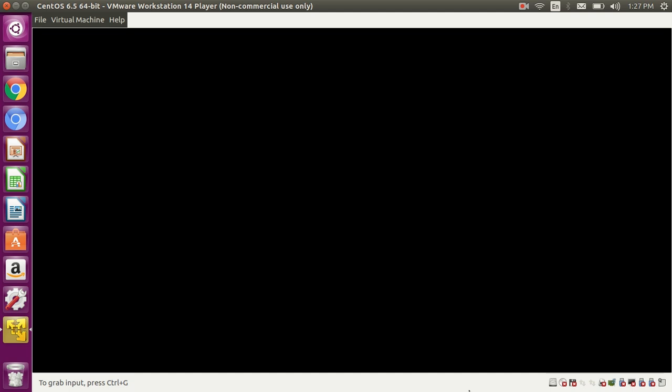I'll just give the DEF in the mail and say I want the timing path clean. I'll CC all the big managers and say please find this DEF, run the PNR on this, and I want the timing clean. With the DEF itself you can't do it. You need the netlist and SDCs. He'll give the netlist, SDCs, everything. Still you can do it.